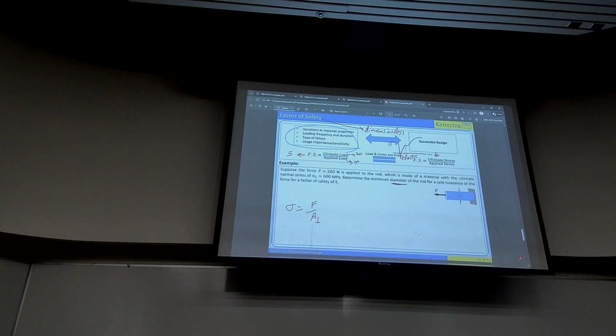Very good. You push the material to its limit. So you equate the max values. So you say sigma U should be sigma max, because max is all about normal stress. So the max normal stress that you observe versus what the material can withstand should be equal. So sigma max is this. We equate this with sigma U.